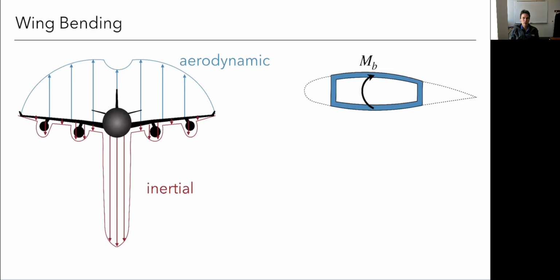So I've created this bending moment in this airfoil, right? It's just a slice. We often will picture an airfoil structure this way. These are those spar caps that we saw, and then the skin is going to be much thicker here. These are often called spar caps in between here and here. There's generally very little structure. So this is what's called a box beam structure. So it looks like a box, and it's going to extend along the wing like a beam.